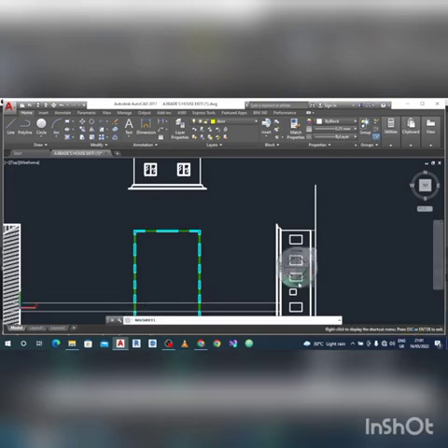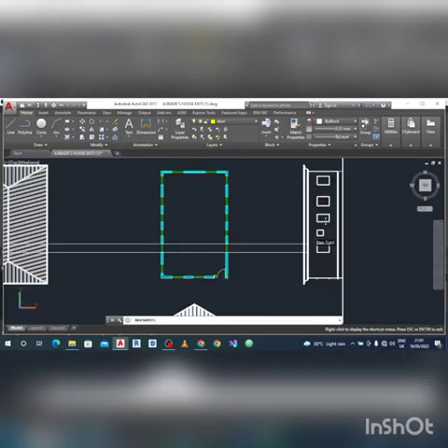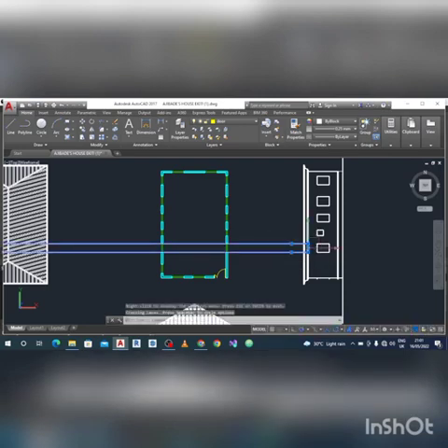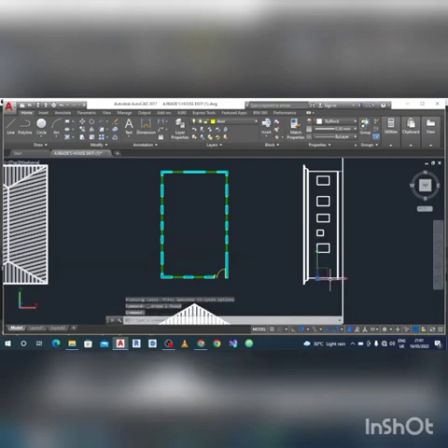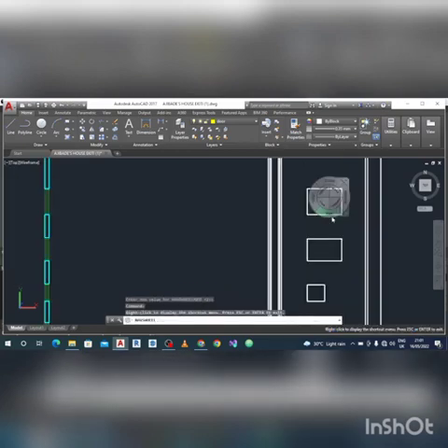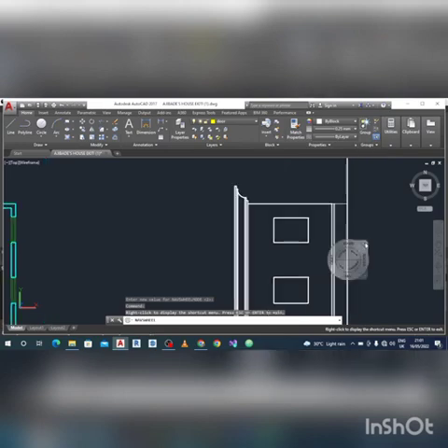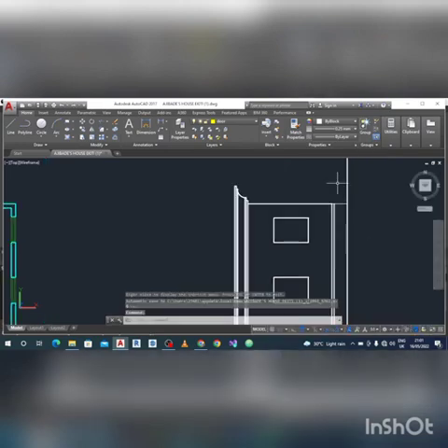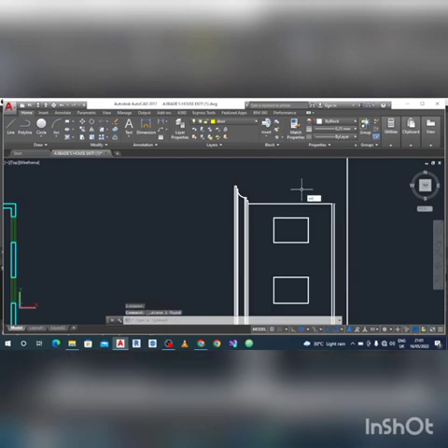Do not forget to always delete lines that are cutting through each other, that are cutting across each other. Do not forget to delete. So then yeah, these extra lines here, we do not need them, so delete as well. So once we're done, what else is remaining? Okay, I think I need to extend this line, so I'll just delete this, then extend. That's EX, enter.